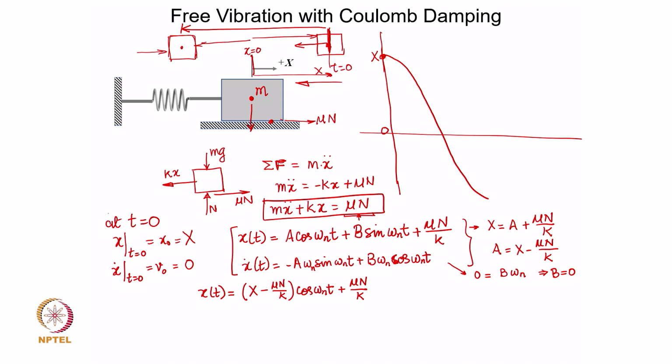Okay. Now, you should note here that this is the solution of the governing equation of motion when the mass moves from right to left. Please make a note here that this direction of the friction force has been taken considering that the motion happens from right to the left, right. In a typical oscillation of a vibratory system, this is just half the cycle, right.